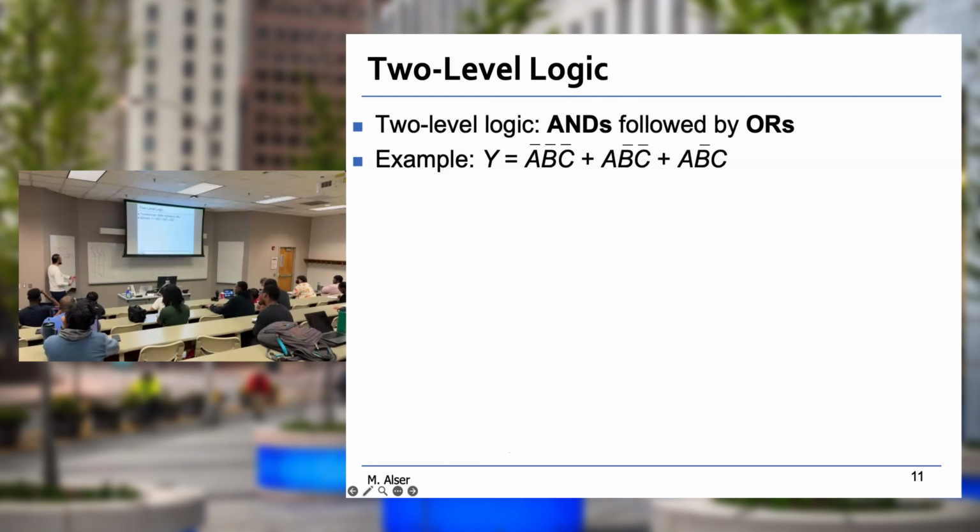Now, if we count, how many NOT gates do we have in here? 1, 2, 3. These are just a wire, okay, taking the same value. Remember, we have the output, single output, going to N inputs, which is allowed. There's no problem with that. Okay, don't connect output with another output. That's not allowed. How many NOT gates do we have here? 6, which is expensive. You need to buy more gates from the market. Here is cheaper. You just need more wires, which is the same case over here. You need wires still, right? Good? Okay.